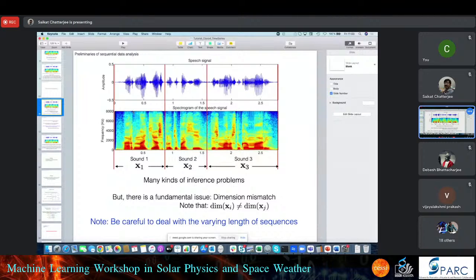Time varying means some parameters of this signal are changing. So here the frequency parameters of the signal are changing with respect to time. Do you see that? For example, here these are the most dominant frequencies. Then here these are the dominant frequencies. You see now more or less 3 bands. There is a low pass band also very clear, like this.